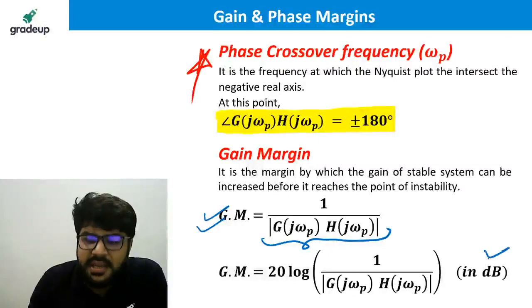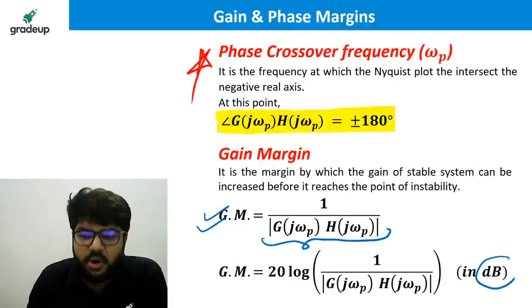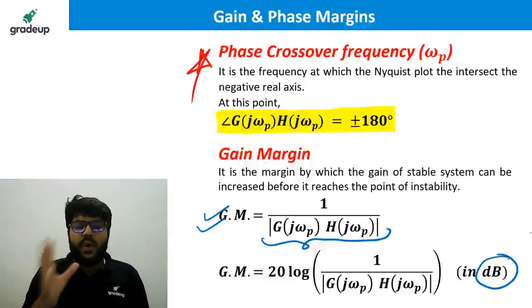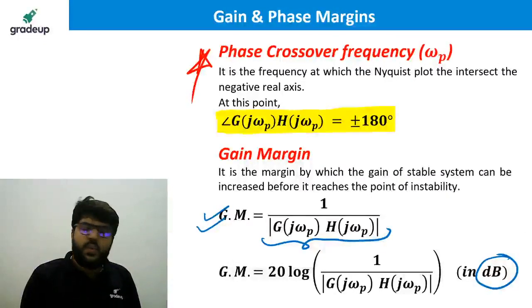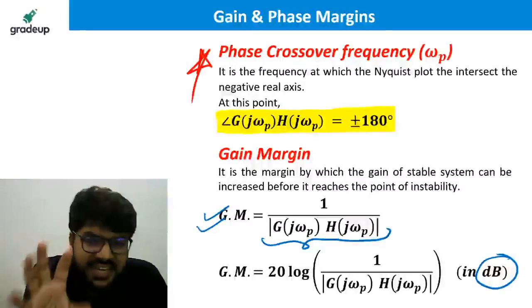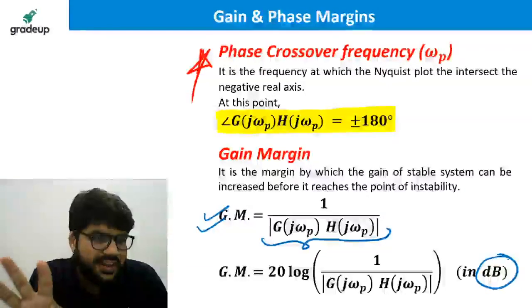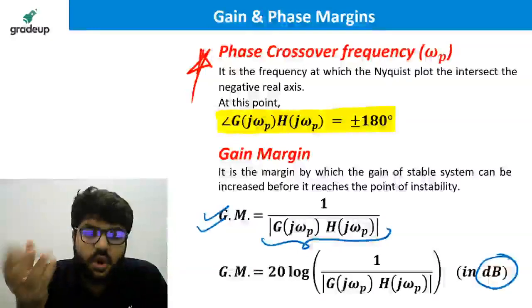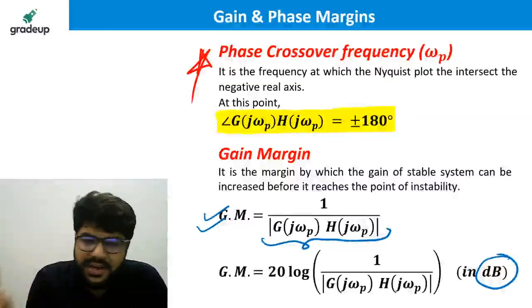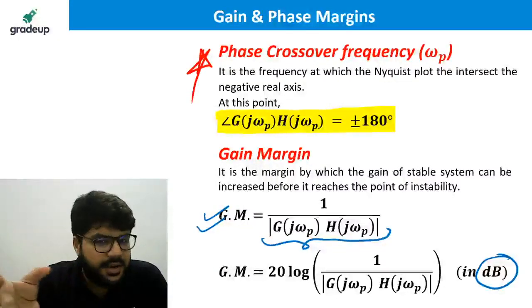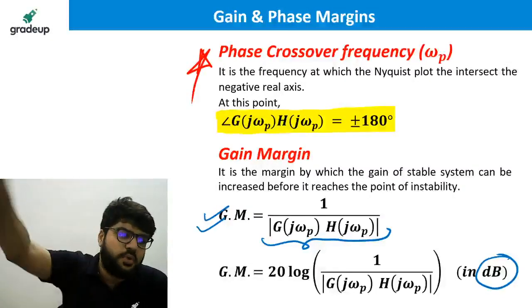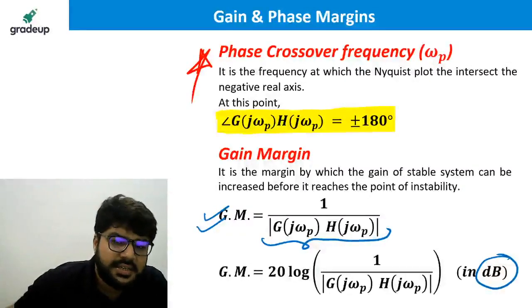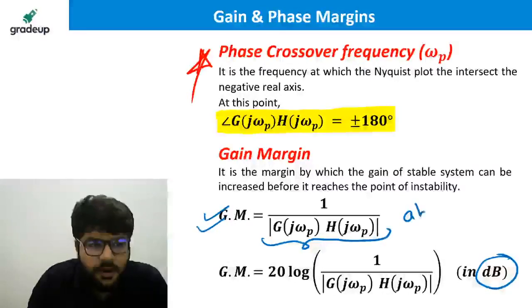So the gain margin such that the system remains stable is also given in the decibel form. Now, I told you I will be talking about logs and decibel. Why decibel is important, why do we use log and all, I'll make everything clear once I start the Bode plots tomorrow. Why log, what is the importance, what all you can achieve by taking log, why the decibel scale is taken, I will explain tomorrow. But because we are also going to refer to the gain margins from the Bode plots, commonly the gain margin in this form is known as the absolute form.